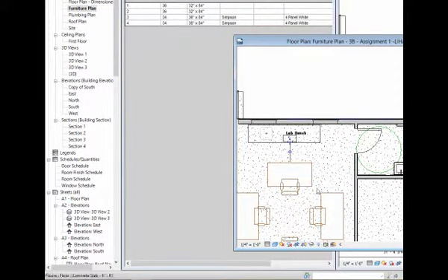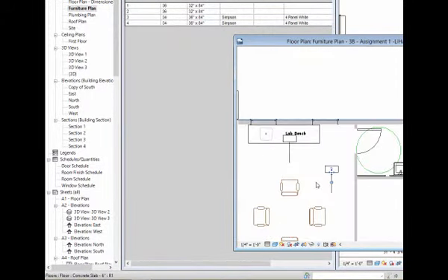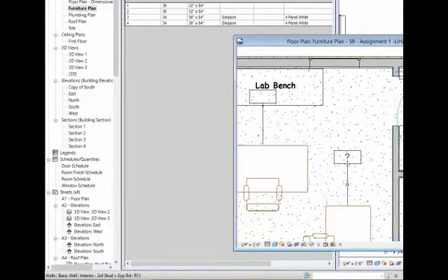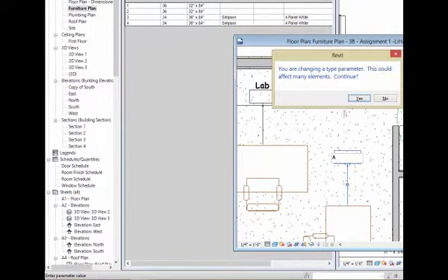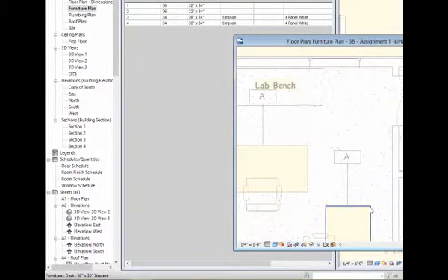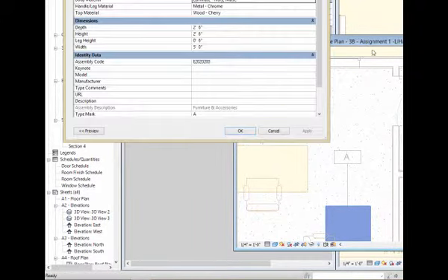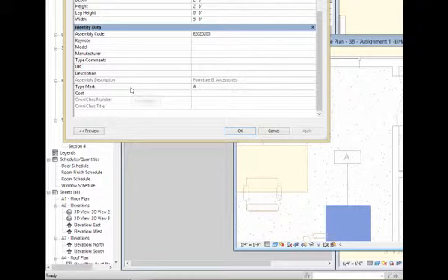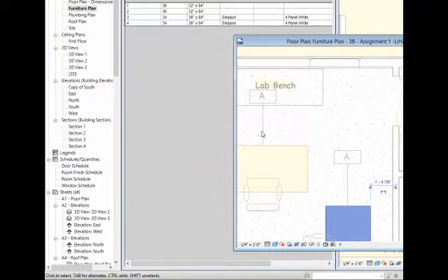So with that, now I can tag that. This is desk number, well, looks like whatever it is. It's not really advertised just yet. It's probably the description. Let me kind of fill that tag in. I'm going to call this desk A. See if that makes any sense. Tags actually are used to fill in values in there too. So looks like that is desk A type 2. So if I go here, let me see what I'm actually filling in. Under the types, it looks like that is just the type mark. So it's an identifier to say there's desk A versus desk B, different types that we could be ordering.